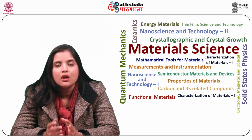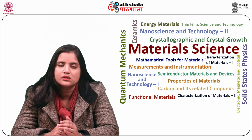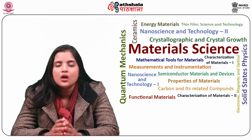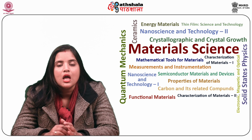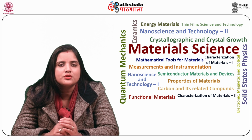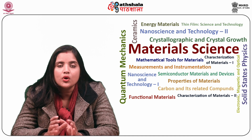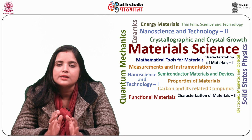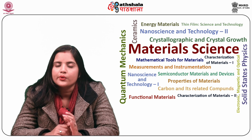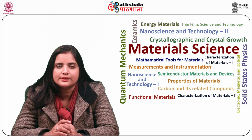Chemical vapor deposition is employed for improving corrosion and wear resistance of the materials. Typical depositions include nickel, tungsten, chromium, and titanium carbide. CVD has numerous benefits as a thin film deposition technique. The chief advantage is that the films grown by this method are conformal, which implies that the thickness of the film on side walls of the objects is similar to that on the top. Consequently, films are uniformly coated on highly bent pieces.